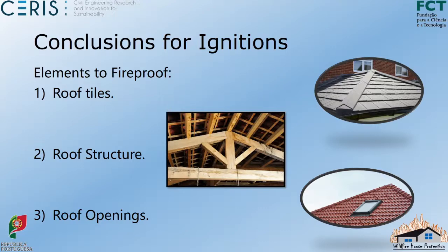And this is not a problem of direct contact with the wildfire, as we talked before, because hardly the roofs get hit by the flames. The problem is the projection of firebrands that accumulate on the roof. Okay, so imagine a lot of firebrands accumulating near this opening may promote an ignition if this opening is not fireproof. Okay, so our recommendation, do not use openings in roofs.